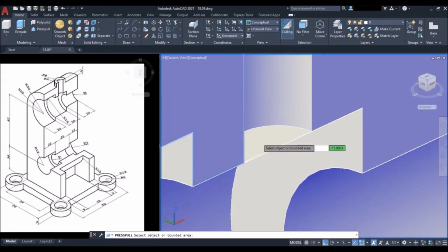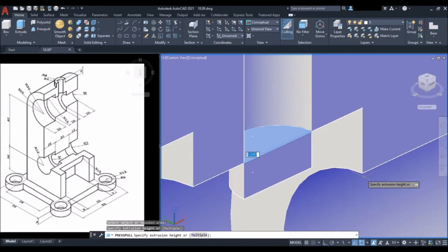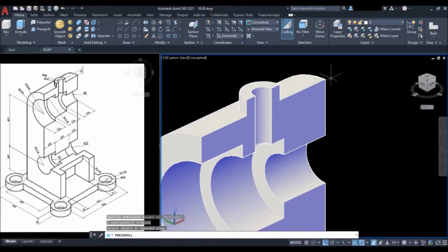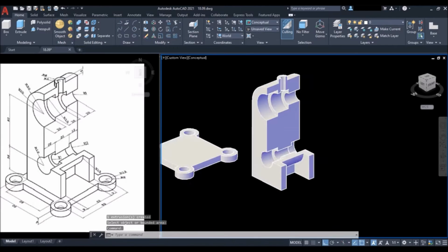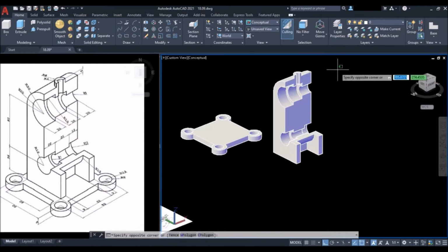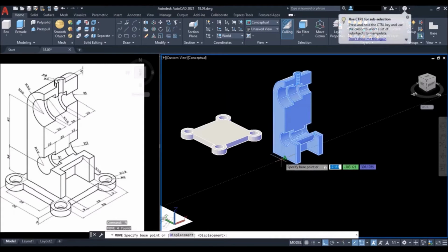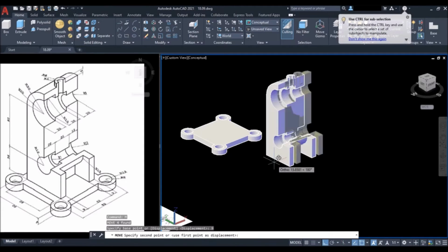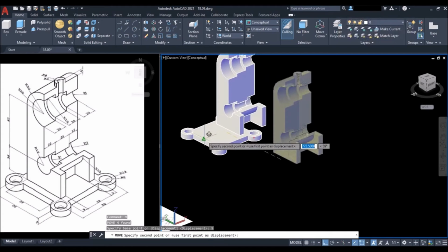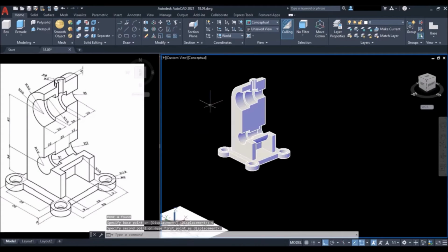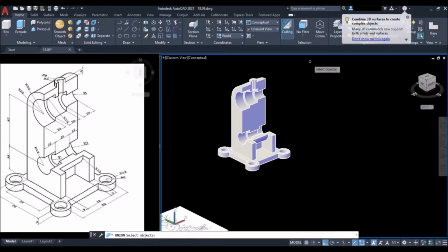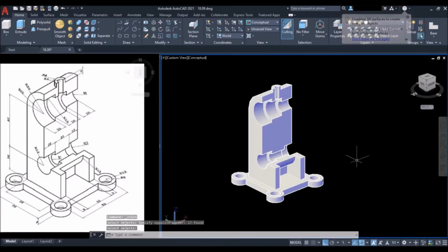Okay, I'll press pull this downwards. Now it's done. So select this part. We need to place it at 9 units from this face. So click on move tool or type M and press enter. Take an extension of 9 units towards this side as shown. Then click at this midpoint snap. Now click on union tool, select the complete model and press enter to union this into one element. So that's it.